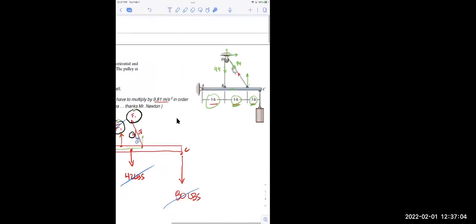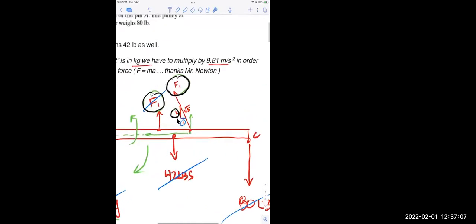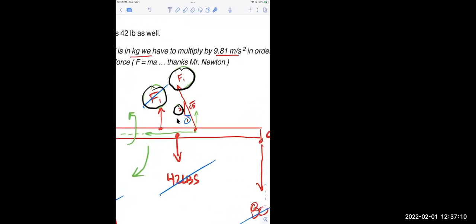And I think it's not obvious, but cool that I redrew. I think this was a good time to redraw the free body diagram because, as I said, the beam doesn't know there's a pulley up there. It just knows that it has a couple of forces pulling on it. That's all it feels, if you will. It doesn't know they're the same. You do, because it's actually a pulley. And that would have made this a lot worse, actually, if that was just 2 different wires that were hooked to the ceiling in random locations, in which case they weren't equalized. That would have made this problem harder.